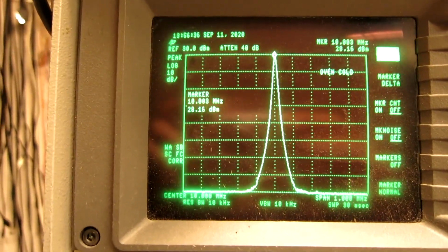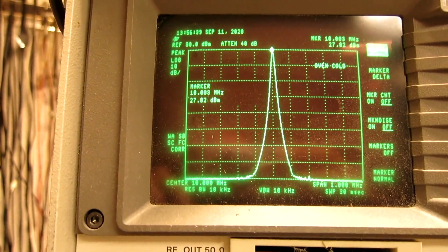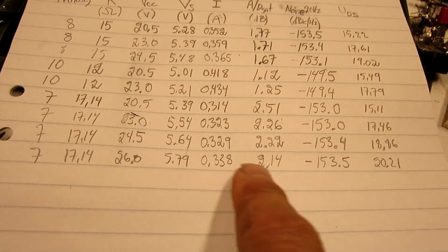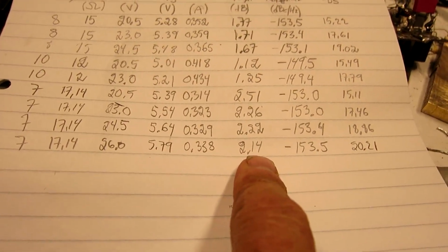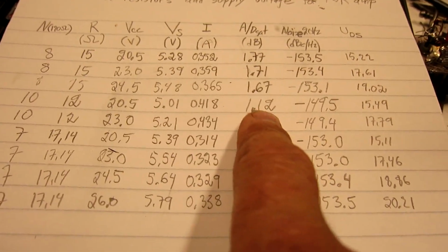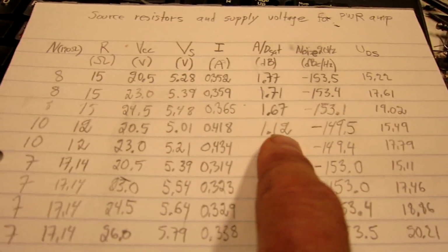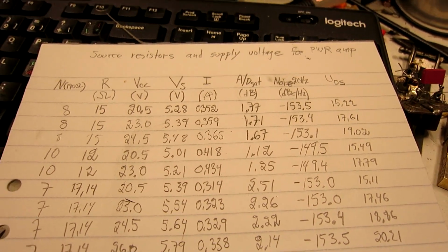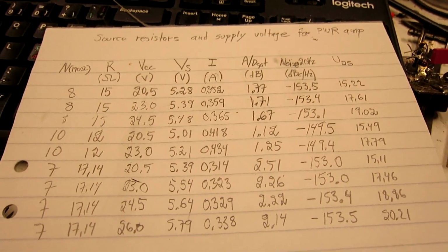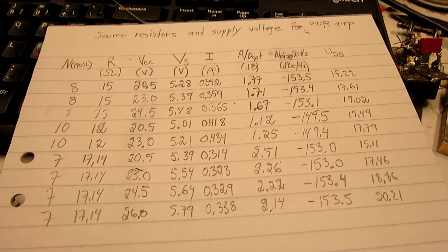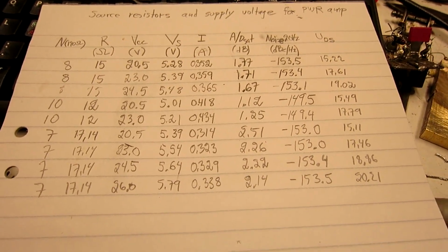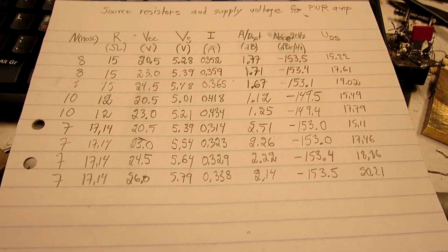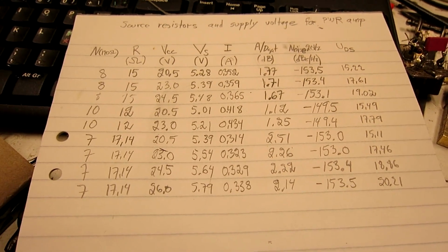The power is 28 dBm, 0.3 or so. And it's this case. So with 12 ohms and 20.5 volts, I have 1 decibel more. That's 29.3 or so. So the power is in the right ballpark, but the waveforms don't look nice. I will have to check the tuning, because I may have touched that while doing other experiments.